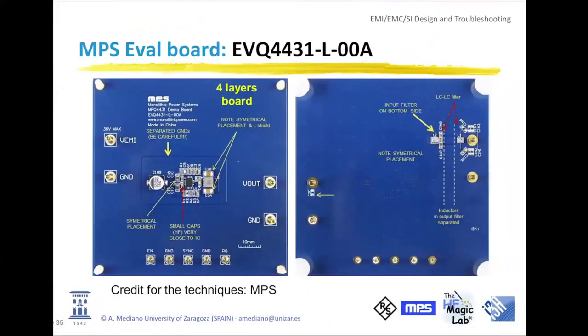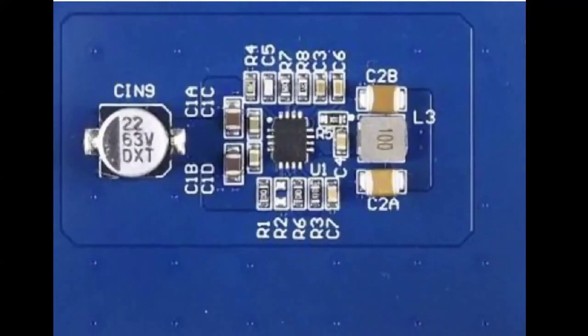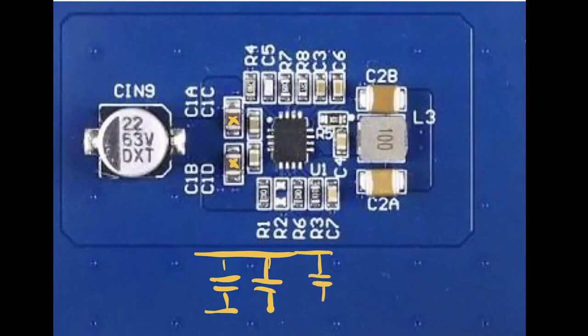Look at this. You have these ideas in your slides, but let me show you the top area of the PCB. In the top area of the PCB, you will find the decoupling capacitors, the 4 decoupling capacitors, let me draw here. Let me reduce the size of the X. You will find 2 big capacitors, this one and this one, and later 2 smaller capacitors to work at higher frequencies, this one and this one. And you can see that one symmetrically in this position to the input voltage. The node for the input voltage is this one.